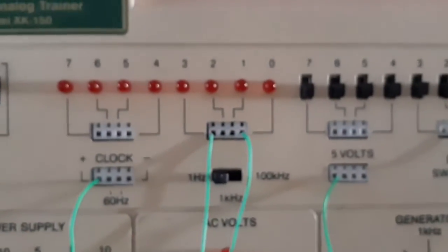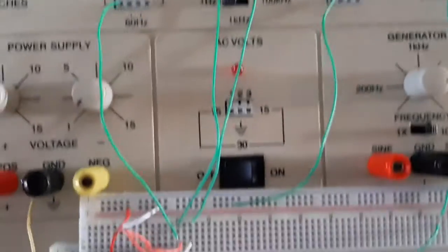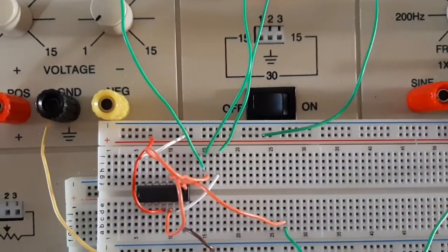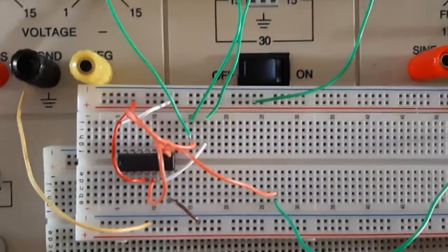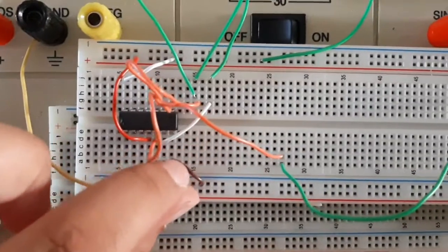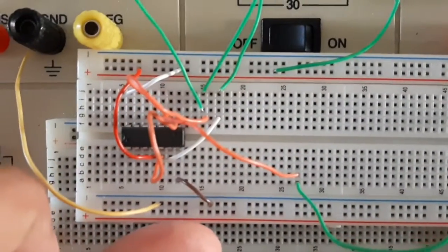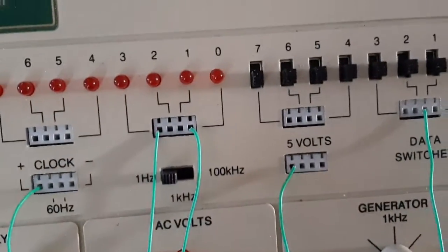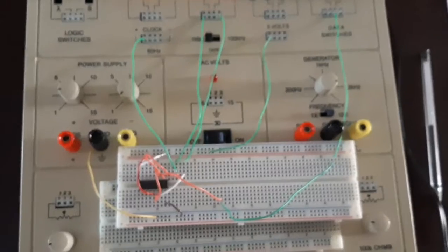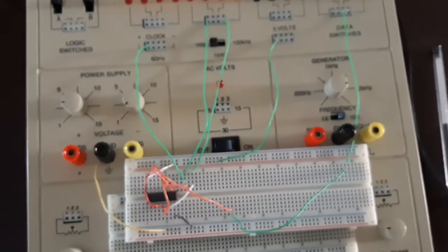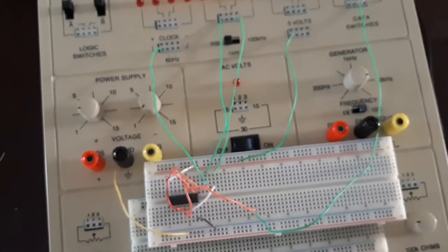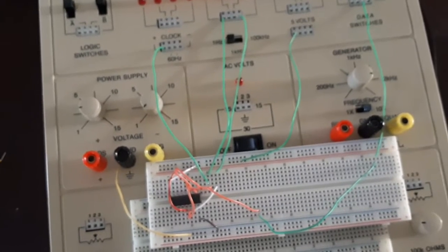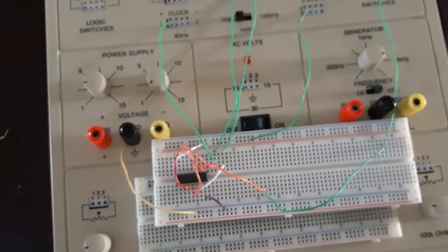Another move I did was that I connected LED number 3 to the 1 Hz, and then I took the output of the second XOR gate, which is pin number 6, and connected it to LED 0. And that is how my circuit is set up. Pin 10 is still connected to switch number 1, which is input A. Pin 4 is still connected to the VCC.